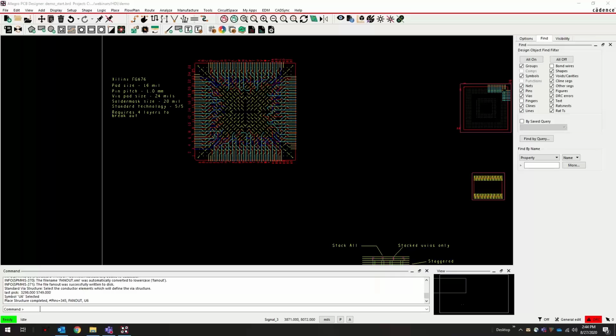Okay, let's see. What is the size of a microvia? So the IPC defines it as a via with a diameter that's less than 6 mils and a pad that's less than 13.8 mils. Okay, thank you.